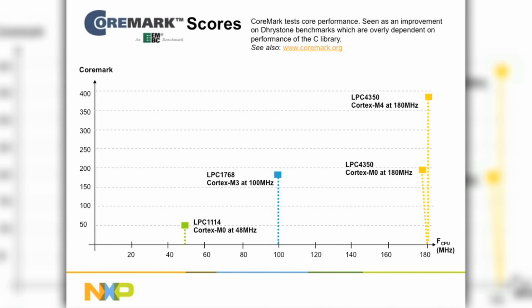It's just not as fast as internal SRAM. NXP has patents around flash acceleration, how we pull data from the flash to basically act almost like a little mini cache. It's not a cache, but it acts that way. So you get more cache hits, and you don't suffer the penalty of slow memory. And so we get very good performance.